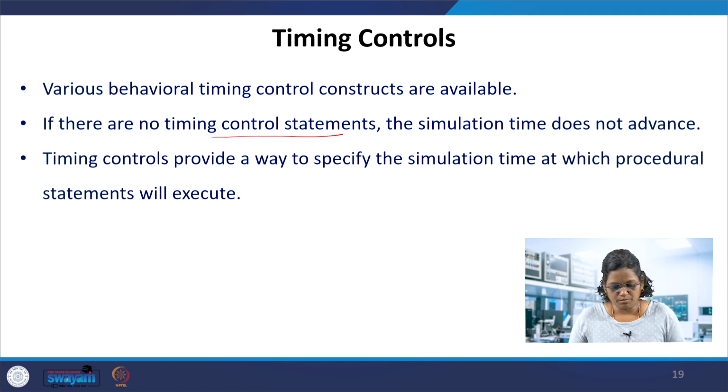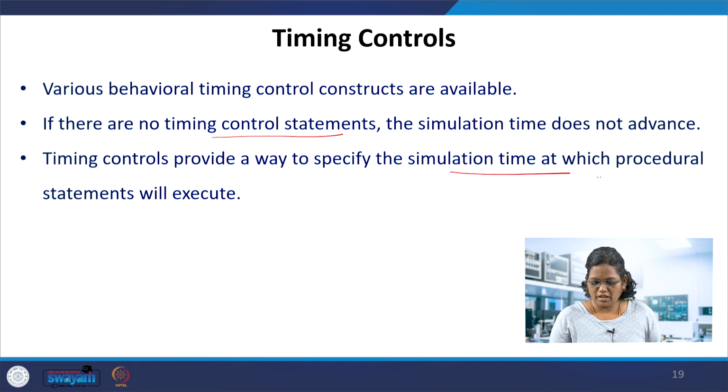So it specifies at which simulation time a procedural statement should be executed. You have 0 nanoseconds, 5 nanoseconds, 10 nanoseconds. The simulator looks at these timing controls at 5 nanoseconds to see what statement is to be executed. So it specifies how the simulation time determines when the Verilog constructs are executed.